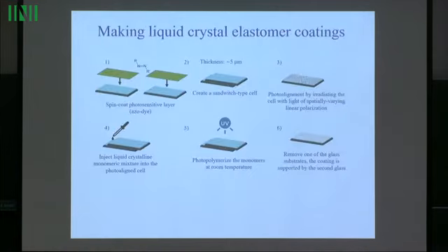So here is how we do the preparation of the film out of this rubber. First we align the substrates by using these plasmonic photomasks that I described to you yesterday. They create identical director field on top and bottom of the sandwich-like cell. And then we fill the gap between these two plates with a monomer mixture, and then we UV polymerize things, and then we remove the top plate, and we are left with the thin film of the liquid crystal elastomer. Typically it's about 10 micrometers.